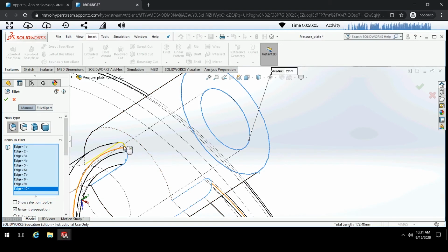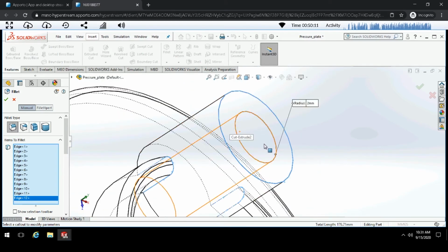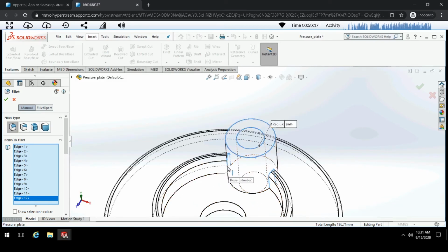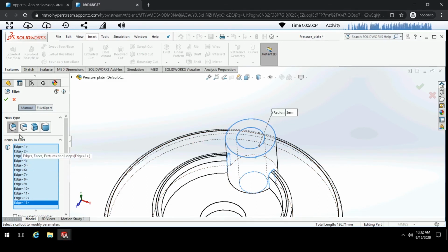Okay, now that you've done that, you want to zoom out and make sure that both the arcs are selected. You have this top edge selected and this top edge selected. And then you're going to hover down here at the base and you'll select this line. So you should have, it's going to say 13 edges. It might also say 5 depending on what your program lets you do, but you can check with the blue highlights. It'll be the top 2 edges and then the arcs and then this bottom edge.